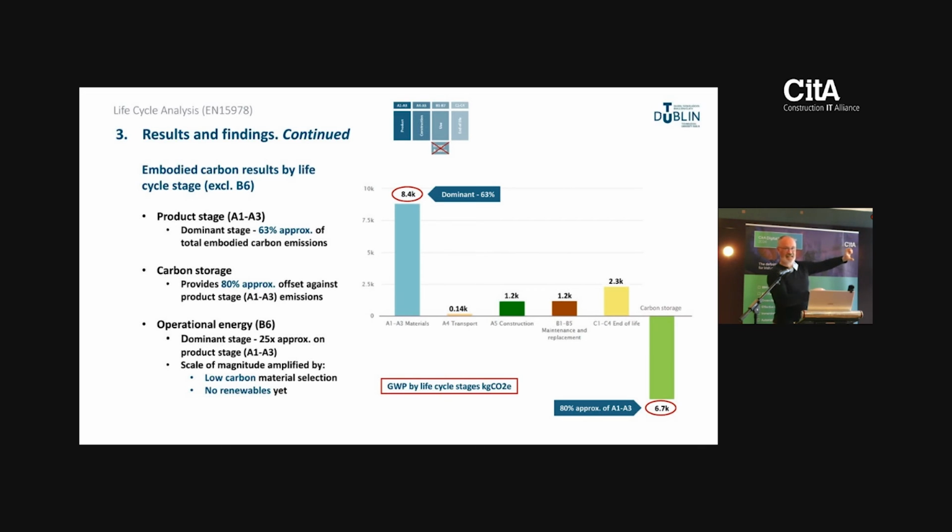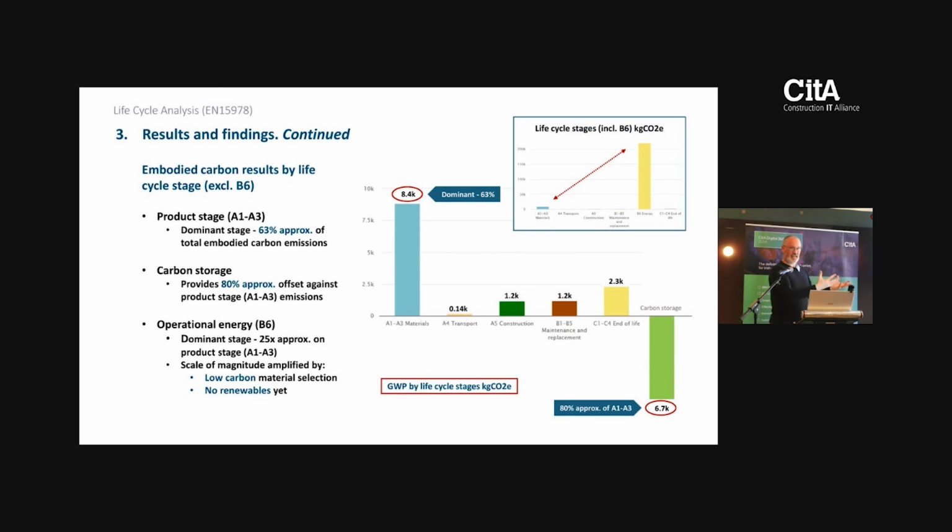So with a 100 mil slab, 500 mil of insulation, which was also the aggregate, which was also the capillary break, we had a wonderful, breathable, insulating material with low embodied carbon for the slab, and the other 500 mil was 100% recycled material, post-consumer waste. So when you start looking at those kind of things, we also had a lot of wood fibers. We had 10 different types of biomaterials, and we had 4 types of post-consumer waste materials.